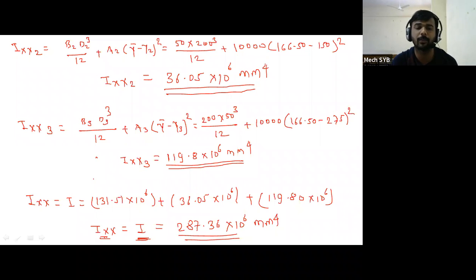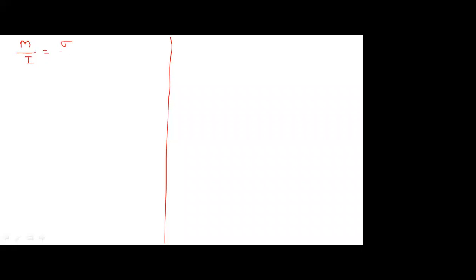That's why purposefully we have calculated this moment of inertia. Okay. Now we have to calculate the bending stress. So how to calculate? Let us see. We have the formula, M upon I is equal to sigma upon y.